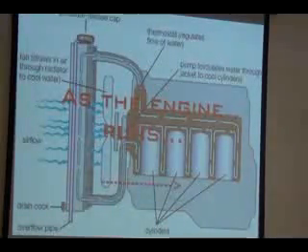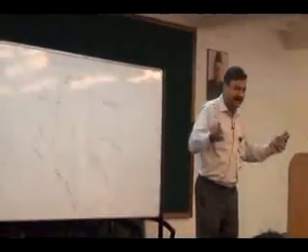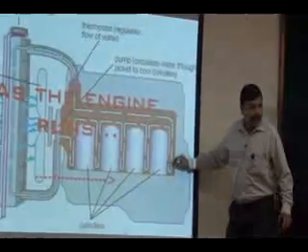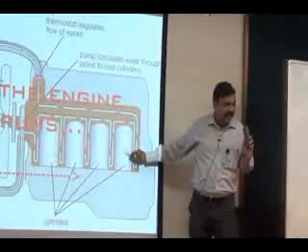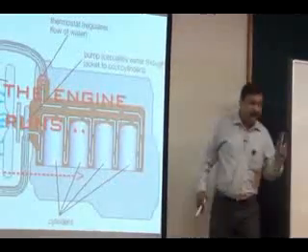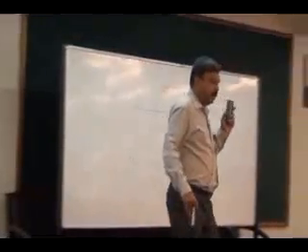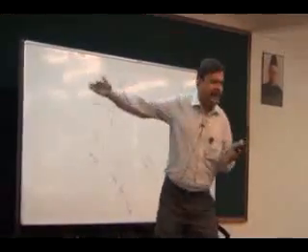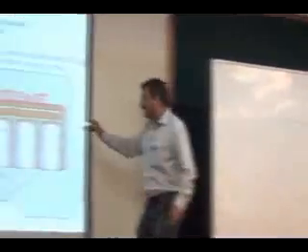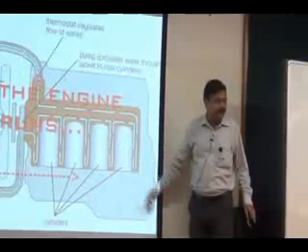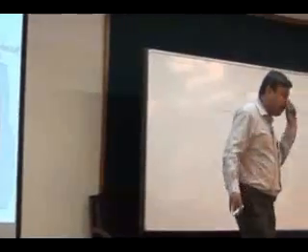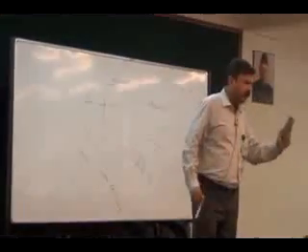Even in your two-wheeler, it is an air-cooled system. Any heavy vehicle engine cylinder has a water jacket. Meaning, this is the cylinder cavity, and I must have a water passage around the cylinder to cool the cylinder cavity. So that makes a lot of difficulties for the product design. How will I make a water cavity here, a water passage here? That puts a big restriction.